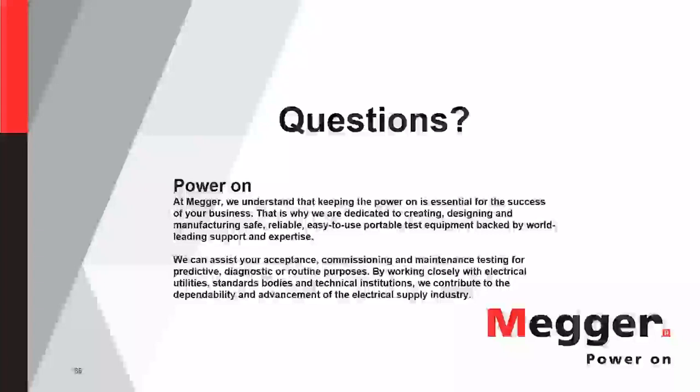And if you think about this breaker, it has a 2-cycle, 3-cycle, 5-cycle interruption, so it's guaranteed to interrupt in there. But I would generally recommend doing contact touch in 10 milliseconds before, because it's previous to that touch. And then most important, of course, is the trip, contact separation in 10 milliseconds afterwards, because you're guaranteed to be in the arcing zone. It might be a little bit short, but that's right there when you want to make sure that your velocity is correct.